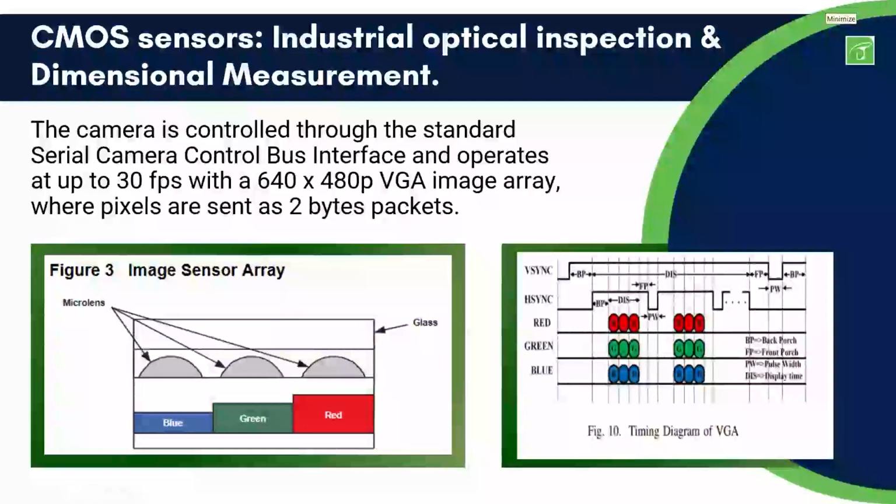If you look at this part accurately, you may see that this is one vertical synchronization. In one vertical synchronization, there is a front porch, back porch, and the display time. So 640 is the actual displaying format. Only 640 is the displaying period. Only in this period can we latch our red, green, and blue components. My back porch and front porch are invalid. You may see that we are passing no data on this timing output diagram. The timing is only displayed on the 640 by 480 resolution output.